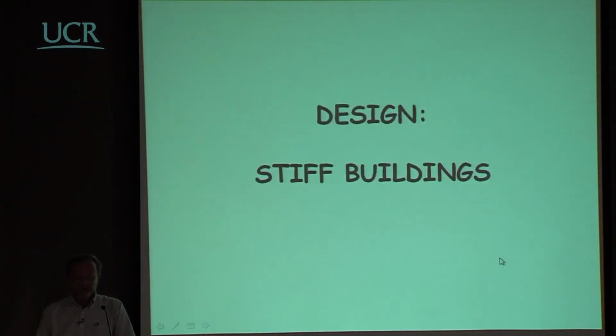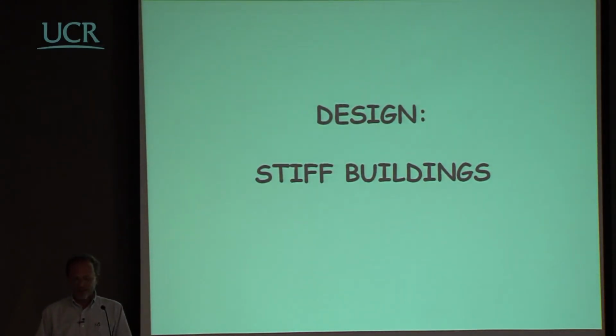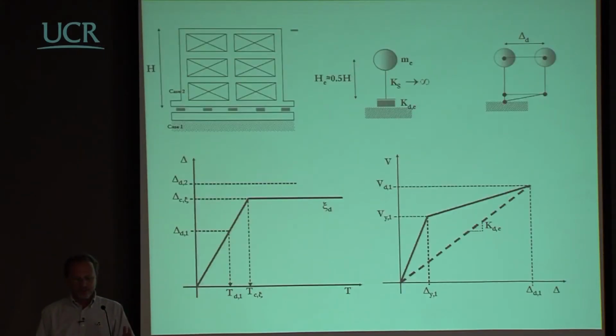But let's go and see, in not more than 10 minutes, the main issues related to design. This has all been introduction, but now 10 minutes of design. Stiff buildings are very easy, very simple. If you assume that a building is very rigid with respect to the isolation system, essentially you are only designing the isolation system.